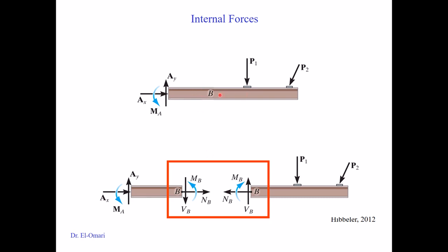When you don't cut, these are the forces that actually resist the failure of the member. They will help in the future in finding the stresses based on the cross section and further design of the member. But the first step is finding these internal reactions or internal forces.